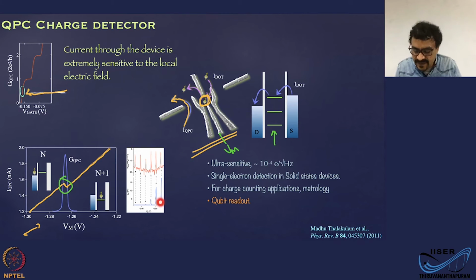And this is technologically really important, because in this range, measuring the electron tunneling event by measuring the current through the dot is almost impossible, because the current levels are in attoamps or even lower. So you cannot measure this current with any of the commercial or even homemade preamplifiers. You cannot measure the current through the dot in this regime. You have to resort to sensing the electrons, or sensing the motion of the electron, and then converting that to current.